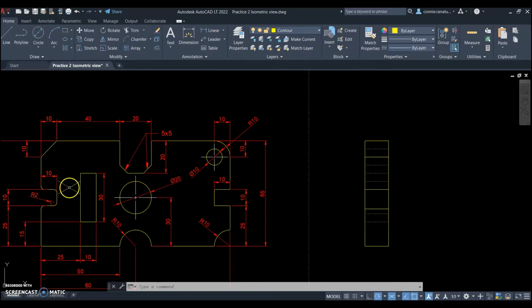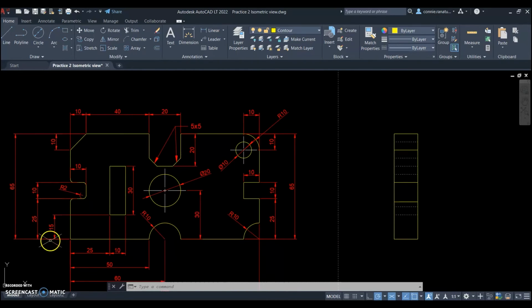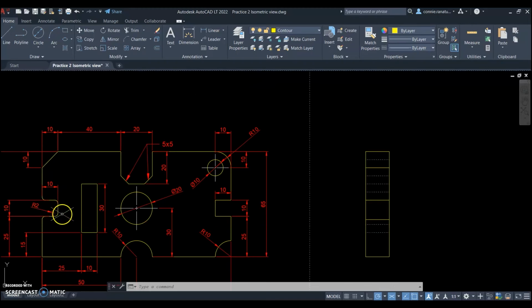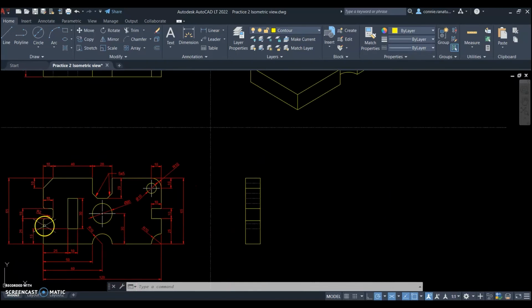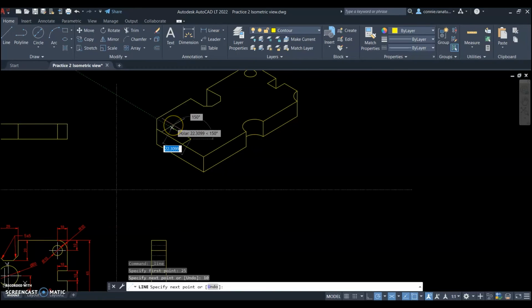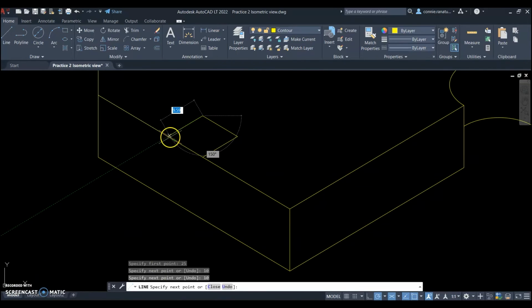And I will make the cut here. And you see it's starting 25 millimeter from that endpoint. And it's going 10 millimeter in. And it's 10 millimeter wide. So I mark the line, mark the endpoint without clicking, move it in the right direction, and I write 25, enter, 10, 10, and 10 into the line here.